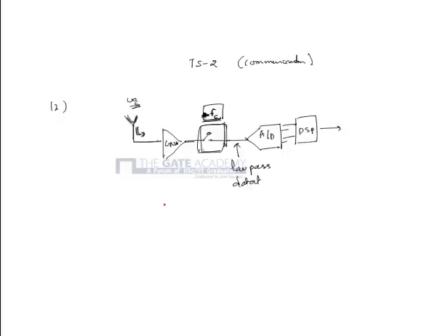Now the question is, the total input power, that is the input power that is fed to the antenna, can vary from minus 100 dBm, let's call it P max, and then P min is minus 10 dBm. These are the two given things in the problem, and it says the gain of the LNA is equal to A. Now these are the given conditions in the problem.